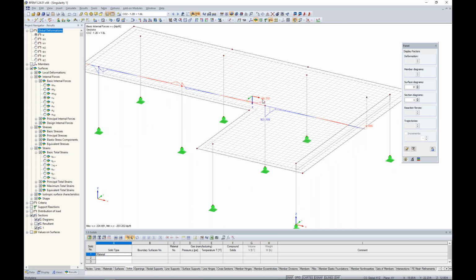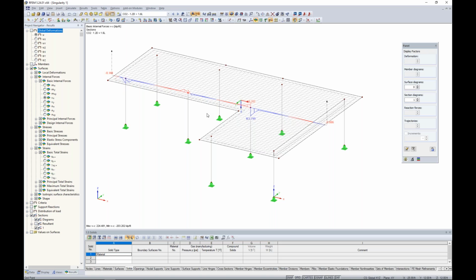We're seeing from negative 66 kips clear up to 163 kips, all at this single point location. So there's got to be a better way to kind of distribute the forces over that entire portion where the column's framing in, because we know in real life it's not represented by this single line element.